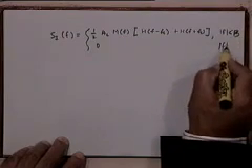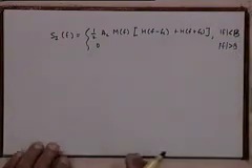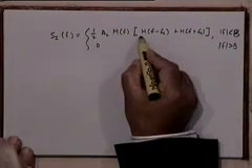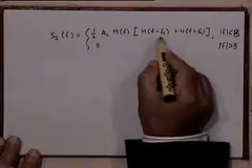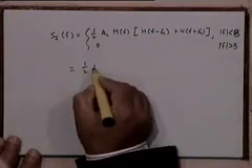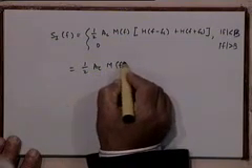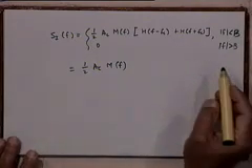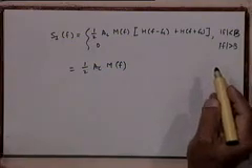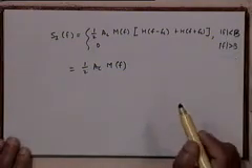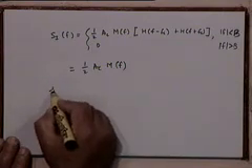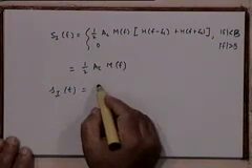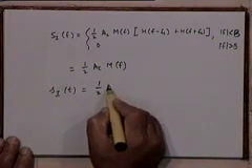So this is what you will get for the spectrum of S_I(f). Now, in view of the fact that this filter is anyway satisfying the constraint that this is equal to 1, this becomes half of A_c times M(f), which itself is limited to |f| < B, because M(f) is supposed to have bandwidth B. So I don't have to qualify this any further. So what does it mean? What is s_I(t)? Half of A_c into m(t).